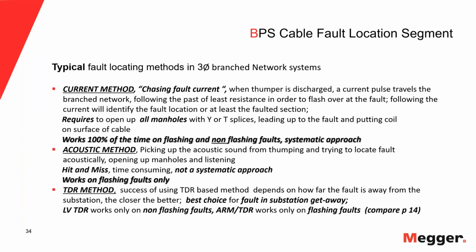And like I say, the TDR method for the most part is not applicable, but I always say try it first, because low voltage TDR gives you impedance differences between phases, which, like in the example I showed you, gave me the indication where to look for the fault, which is very powerful. Basically low voltage means it's non-flashing faults. Or if I do arc reflection, I can do flashing faults. But again, arc reflection is very, very difficult to do on these systems. So these are the three methods.